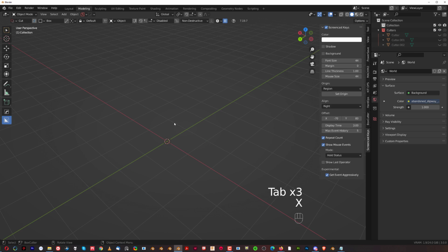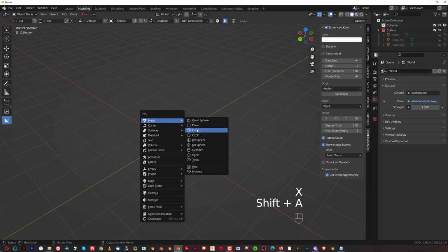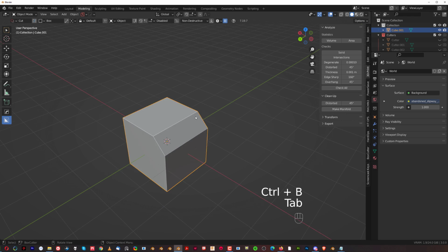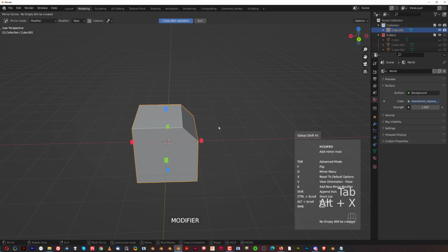And by the way, this mirror tool is great. It's a symmetry mirror in edit mode. So let's say I have some kind of a mesh here like this. I want to symmetrize it. Normally, I would be using Hard Ops. Okay, so Alt X, D, Symmetry, and Symmetrize.